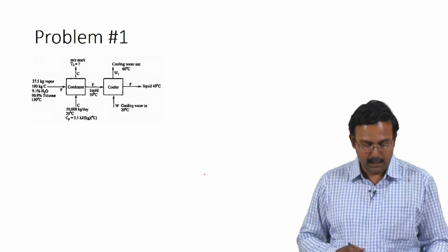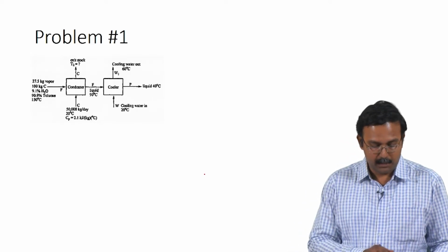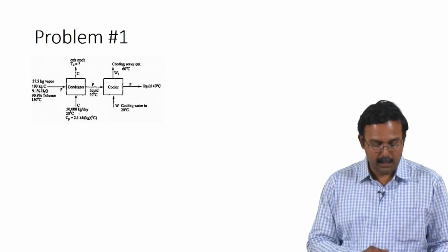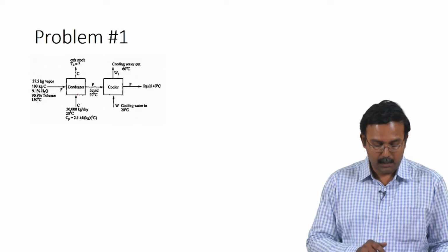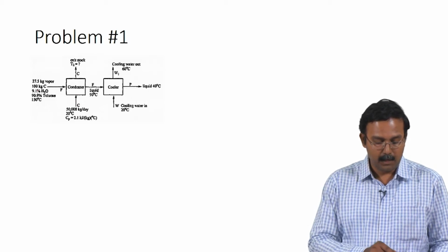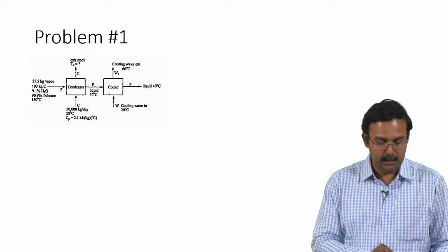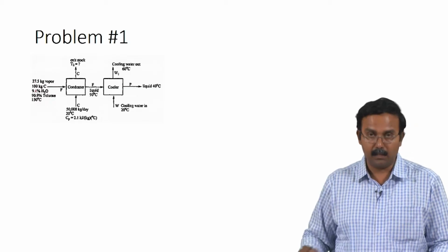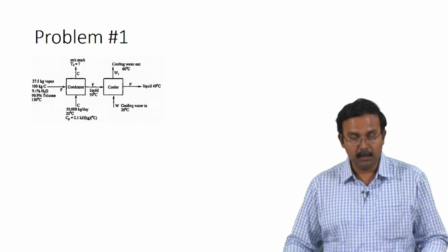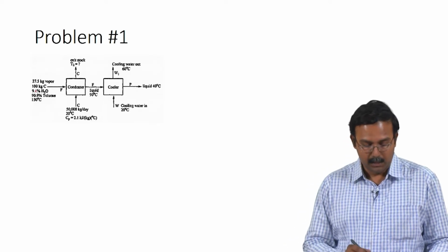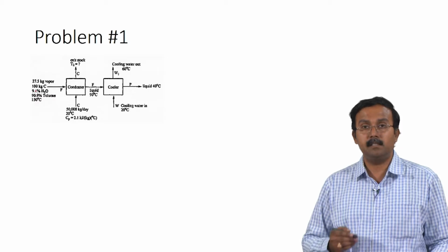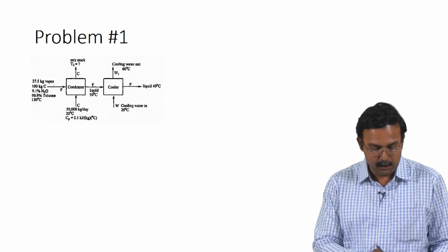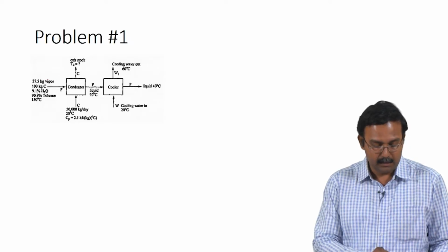So, here is the flow chart. We have the information that we have entered. So, you have 50,000 kilograms per day of coolant coming in, and we know that for every 100 kilograms of coolant you have 27.5 kilograms of vapor which is being fed. So, let us first perform the basic material balance which is required. So, as I always say, material balance is the first step for any energy balance problem. So, let us perform the material balance to get the feed input.